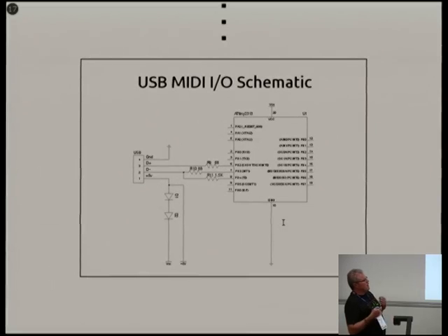USB MIDI. Generally, from a microcontroller point of view, writing a USB device is pretty complex. You need specialized chips, and there are a lot of timing issues. But at the USB 1 level spec, the system is slow enough that you can write it in software. So there's a company that has written an open source product called VUSB, a set of firmware libraries for Atmel chips. In this case, I'm using the ATtiny. Basically, everything becomes software driven.